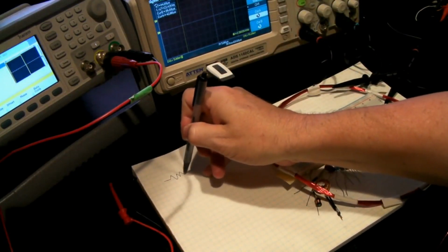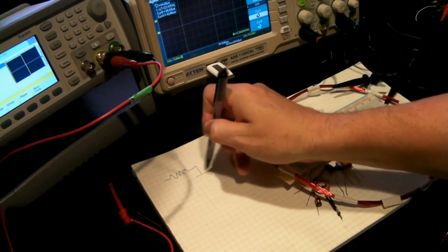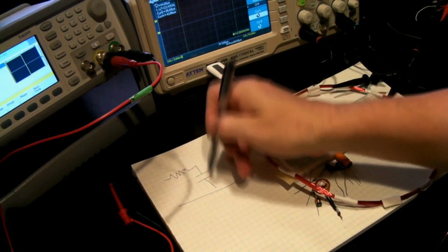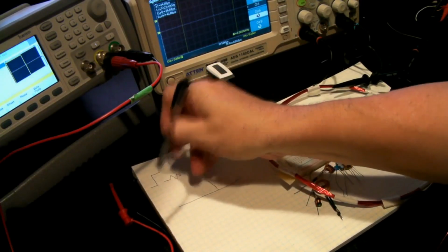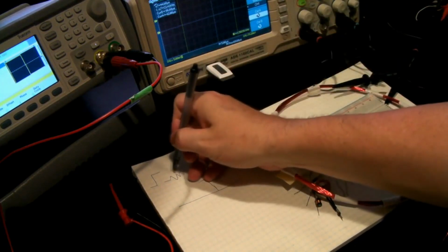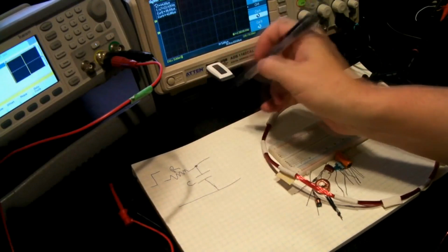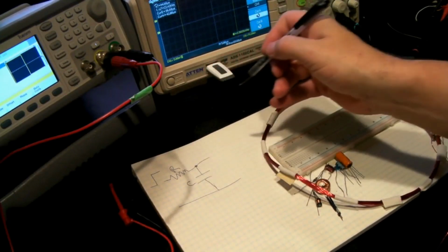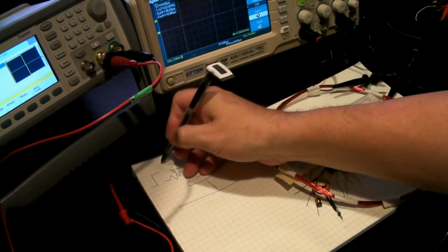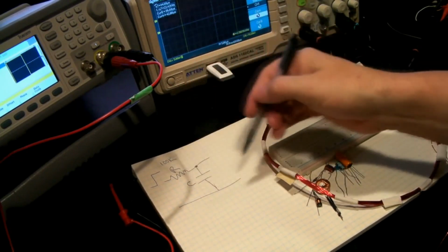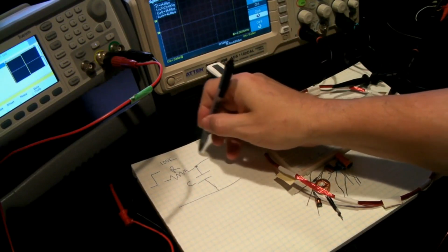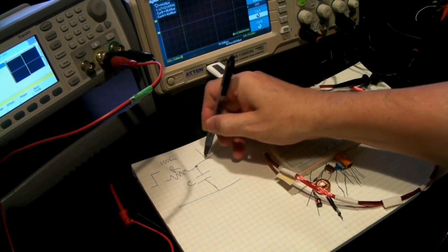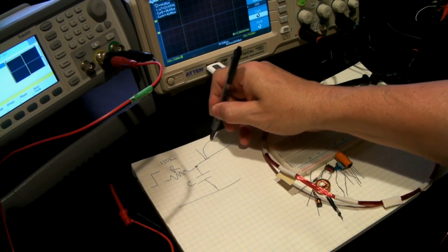If we put a resistor and then a capacitor, and then we measure the oscilloscope here, and we put in a step on the input of the resistor, R, and we have C. If we know what R is, so let's just say 100K, and we don't know what C is, but what will happen is, over time, if we measure this point here, we will get a stepped output, an exponential output. It'll rise and slowly taper off.